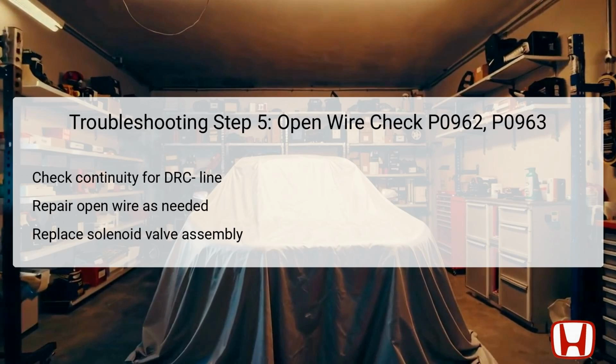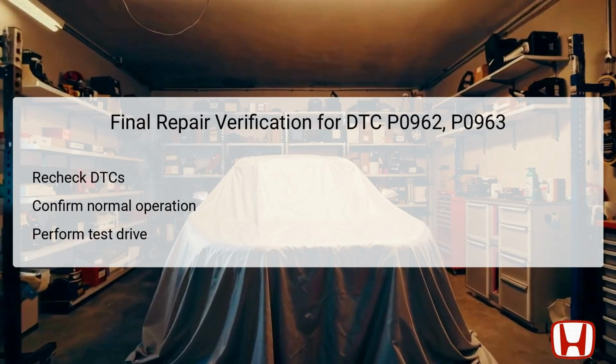cause of the DTCs. After completing all necessary repairs for DTCs P0962 and P0963, it is paramount to conduct a final verification to ensure that the adjustments made have resolved the issue. Start by rechecking the DTCs using the Honda Diagnostic system to ensure that no fault codes reappear, verifying that the electrical circuits are now functioning correctly.